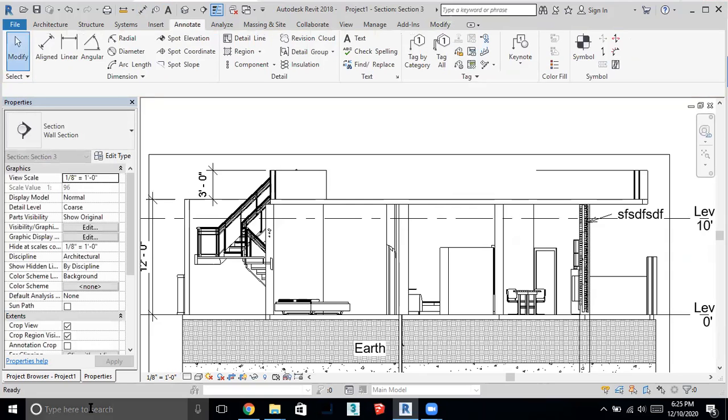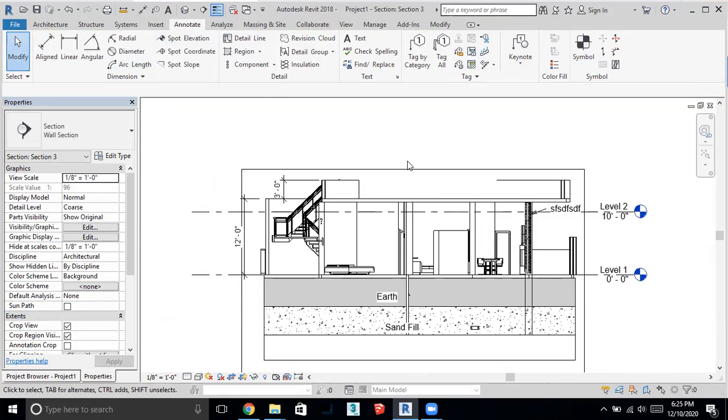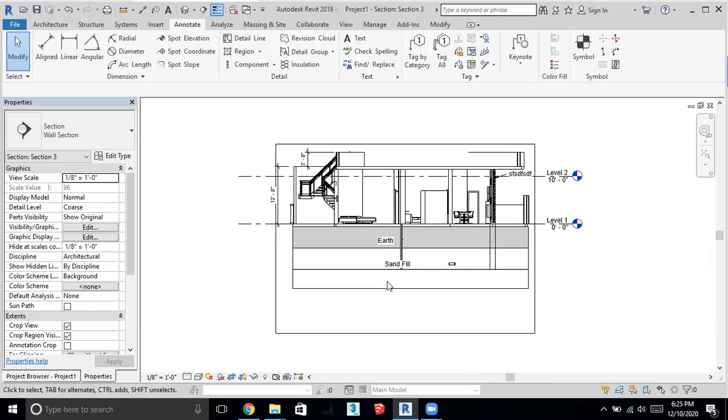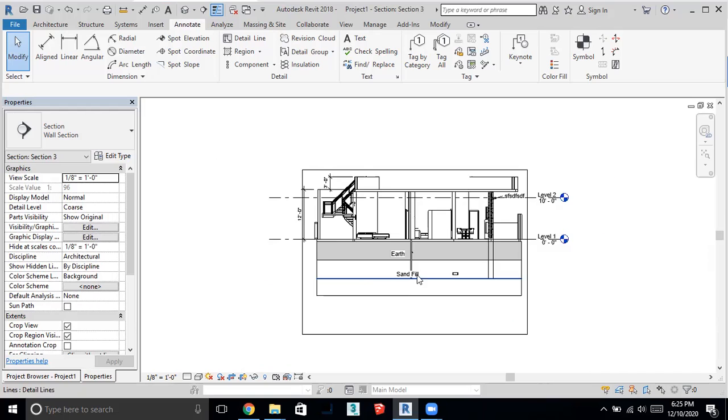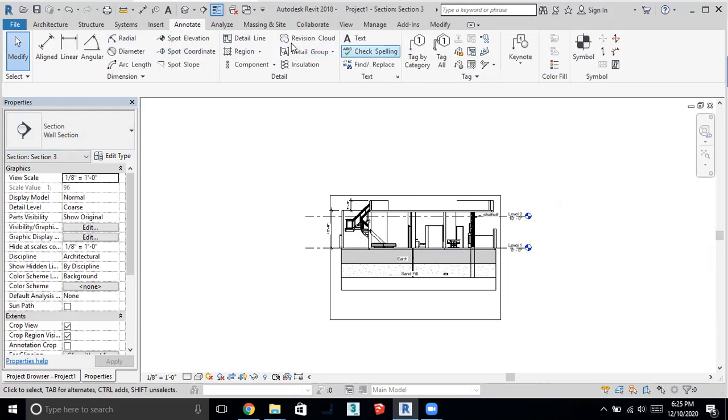Because it's a 2D section, it will allow only that horizontal view, sectional view. Add the dimensions, notes, and everything. This will be the section for your one model. Okay, this is wall section. I have added some information to you. Same with text.